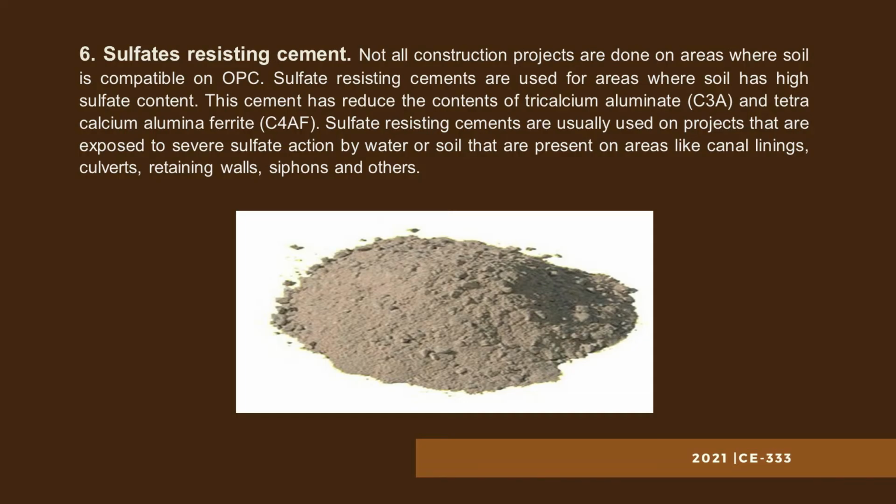Next is sulfate-resisting cement. Not all construction projects are done on areas where soil is compatible with OPC. Sulfate-resisting cements are used for areas where soil has a sulfate content.